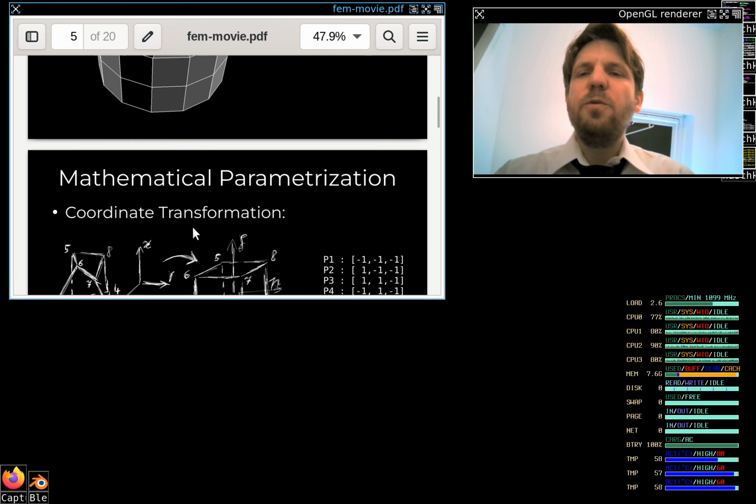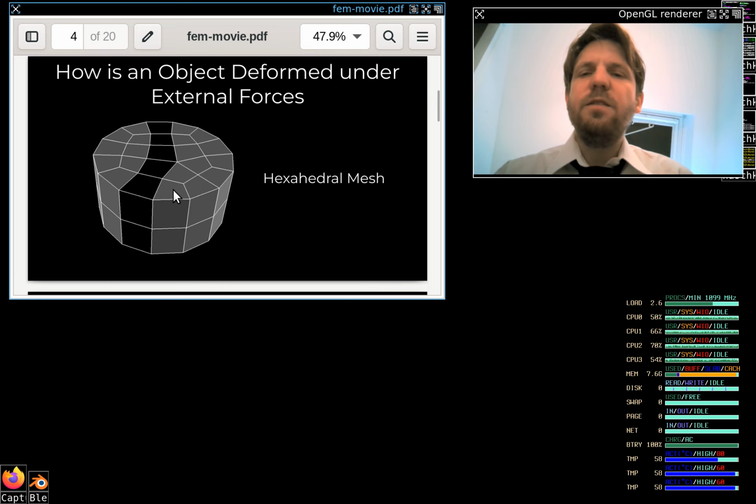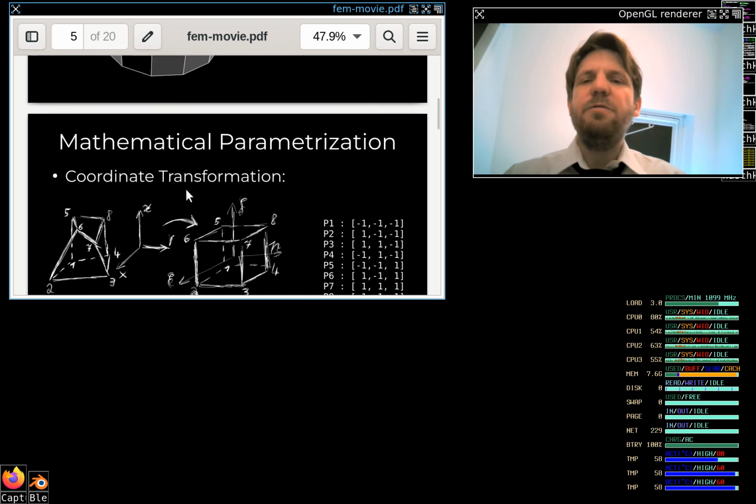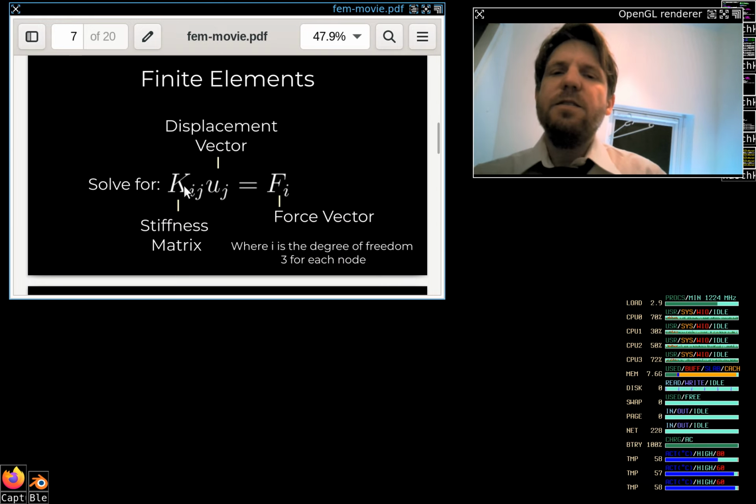Don't worry about this. So you calculate the stiffness matrix for this one, for this one, for this one, and sum it up at this point here in the matrix. Of course this also gives you indices for the other points, but you will get parts of these points from all three elements, and you just sum it up in the global matrix and it will be fine. That's how it works out.